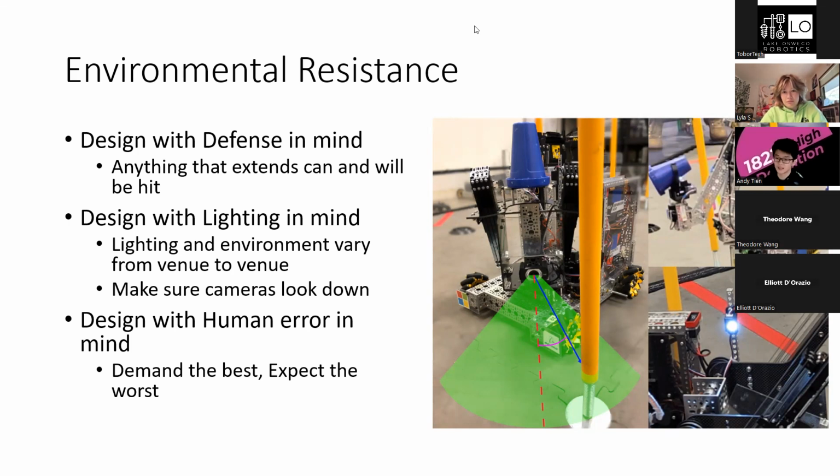So say the intake has a large guide, or the delivery has a large guide. For the Power Play season, one of the criteria we set while designing was that the driver had to be able to have around 4 inches of back and forth tolerance when delivering the pixel on the stage or on the backdrop, so that when our drivers get stressed or there's a misinput, our robot doesn't end up crashing into our backdrop and descoring our elements.